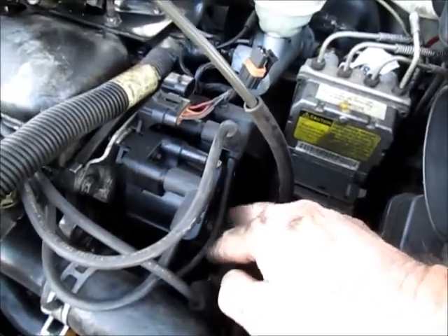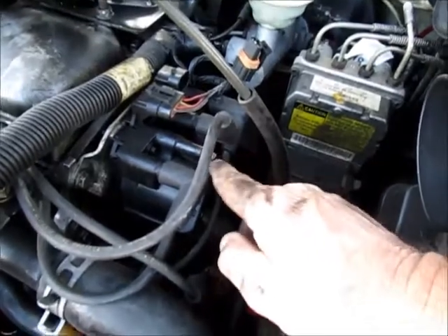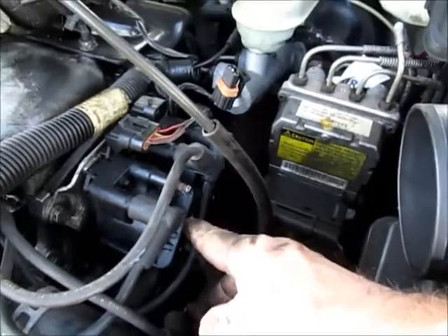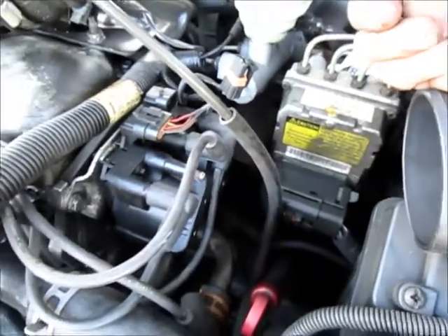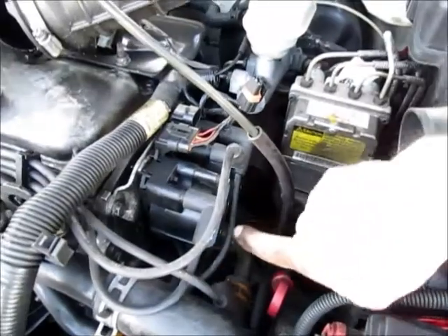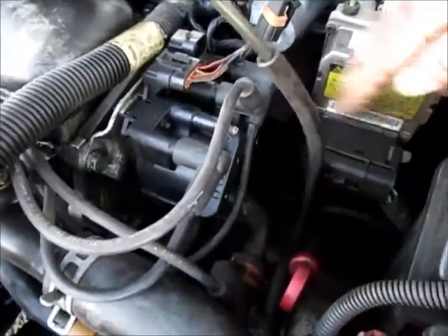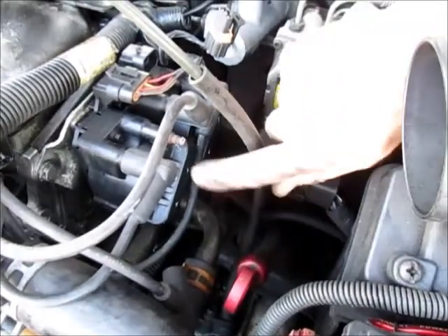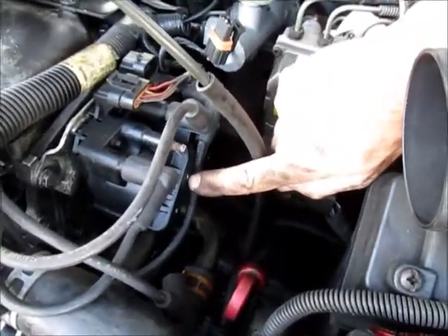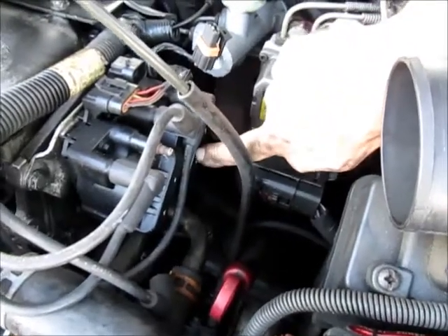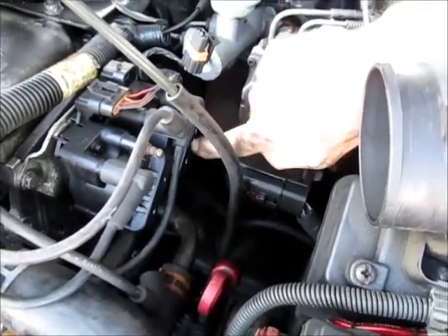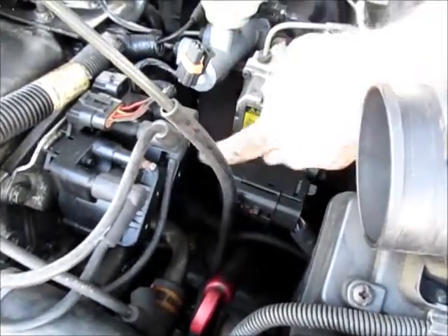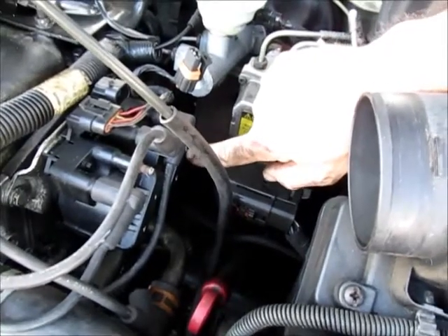So what we're going to do now is, I think that I have a bad coil here. I'm going to move this over to here, move this back, then we're going to clear the codes and rerun the engine again. If this coil is bad, that misfire code is going to go to number 2 cylinder, because I verified that by moving it to the bad point. That coil can't fire number 2 cylinder now, and I'm going to get a P0302 misfire code for number 2. So we're going to do that right now.